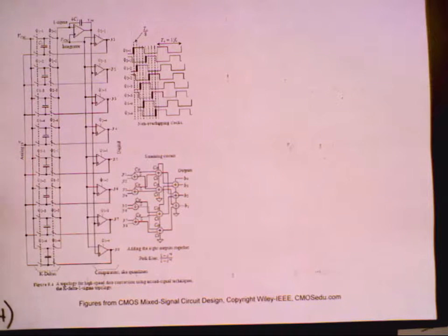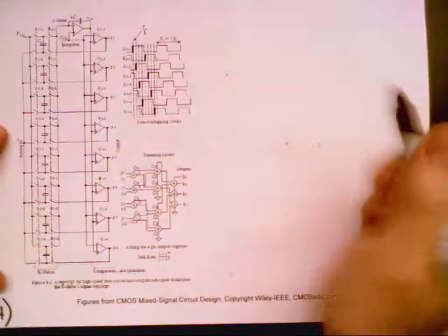Yeah, you throw in the order, right? Another way of answering it is you're applying a filter to all of that data and decimating, and that decimation is causing noise to alias into your baseband spectrum. Does everybody follow that? Are you going to be able to answer what's the difference between serial mode and parallel mode? And give me a simple example. Here, let me give you an example.